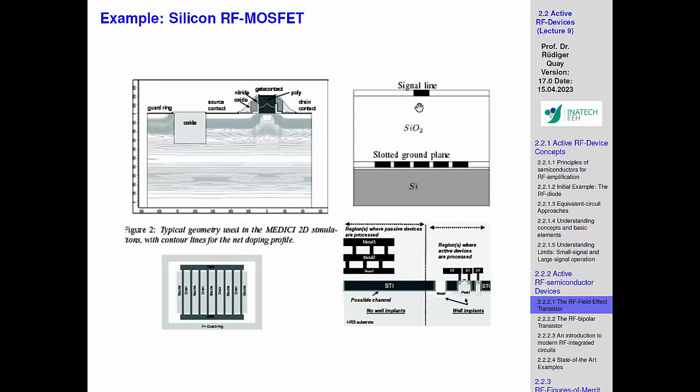And the trick is a bit that if you have very thin layers, that's not so nice, because you shrink the things, and suddenly you realize the impedances you're getting are not so nice. And that's the same here. Silicon dioxide is a very low loss material itself, but the geometries don't fit, because this is only maybe 5 micron thick and not, as a normal wafer, 100 microns. So this is not giving you the right choice, but somehow it works. That's just to give you the flavor of what you have, what the differences are.